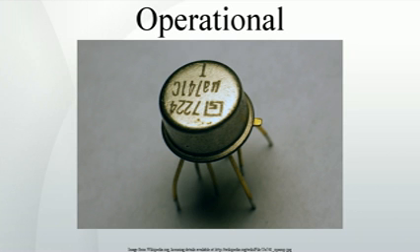Closed loop. If predictable operation is desired, negative feedback is used, by applying a portion of the output voltage to the inverting input. The closed-loop feedback greatly reduces the gain of the circuit. When negative feedback is used, the circuit's overall gain and response becomes determined mostly by the feedback network, rather than by the op-amp characteristics. If the feedback network is made of components with values small relative to the op-amp's input impedance, the value of the op-amp's open-loop response AOL does not seriously affect the